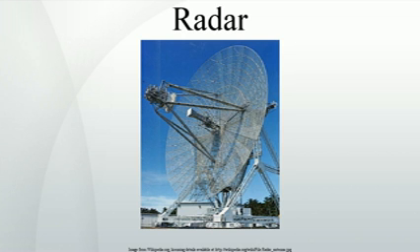The primary purpose is to measure both the amplitude and frequency of the aggregate reflected signal from multiple distances. This is used with weather radar to measure radial wind velocity and precipitation rate in each different volume of air. This is linked with computing systems to produce a real-time electronic weather map. Aircraft safety depends upon continuous access to accurate weather radar information that is used to prevent injuries and accidents.